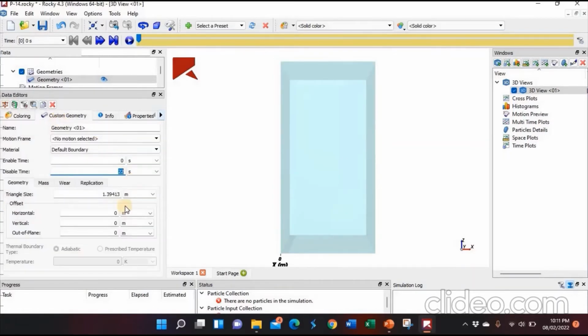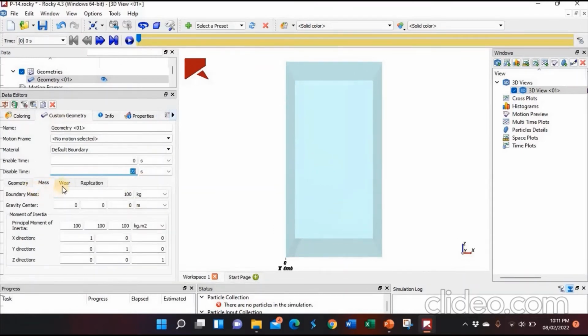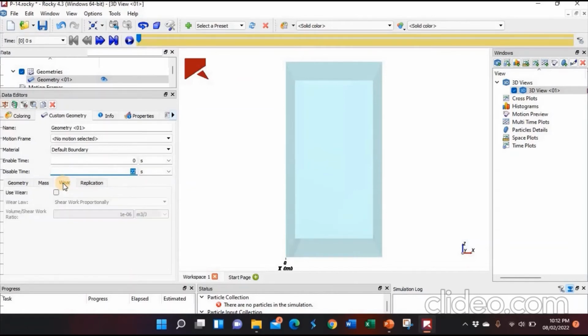Now these are the sections where we can adjust the mass of the boundaries, the mass of the geometry, to any value, meaning 1000 grams, 1000 kg, 100 kg, whatever we say. In this particular case I've changed it to many values, but it doesn't matter, because there is no interaction of the particle with the boundary, and the geometry itself is only there to be filled with the fluid, so whatever value we set, it doesn't matter.